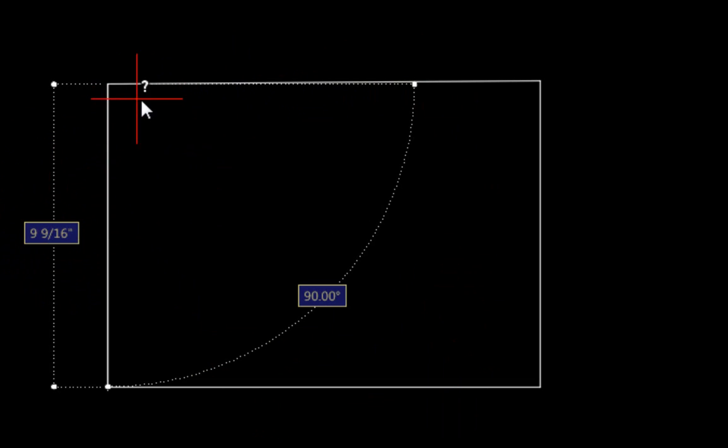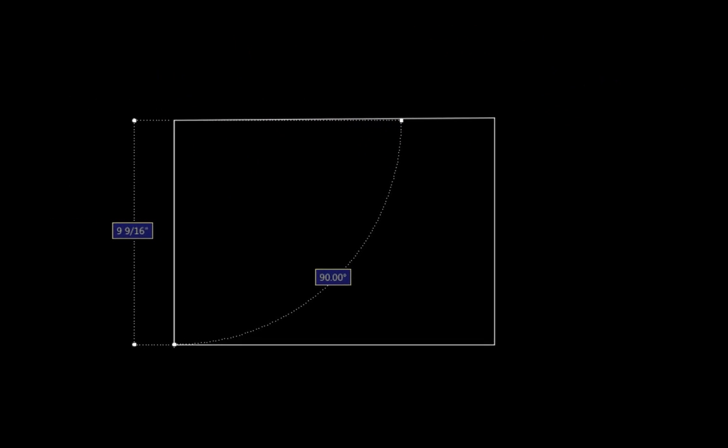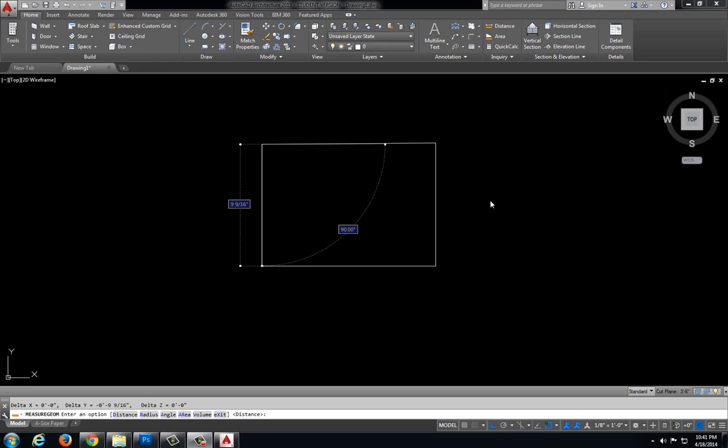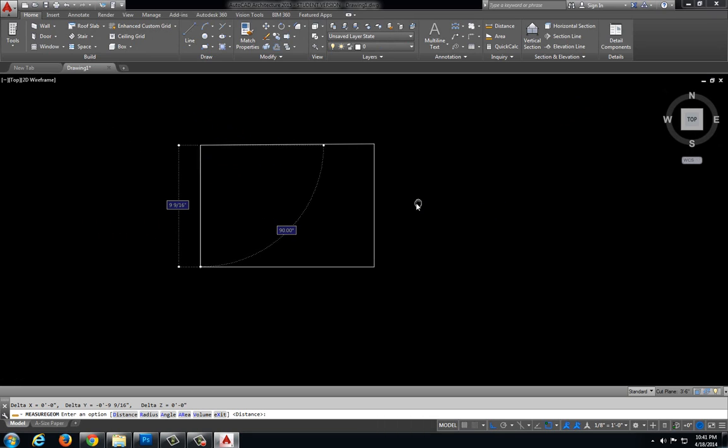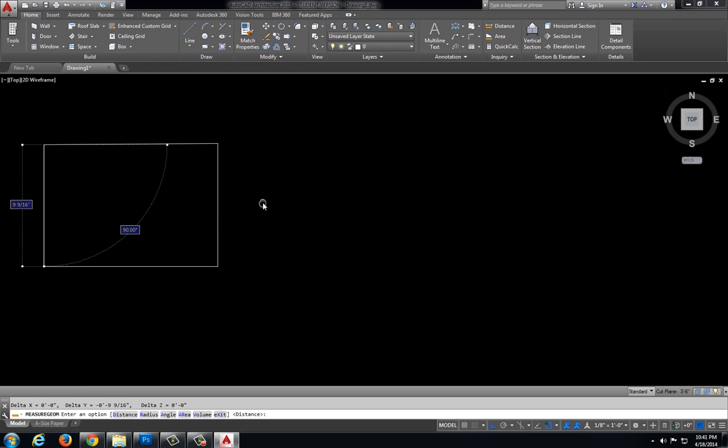These corners are not perfectly 90 degrees up at the top. We know they're 90 degrees down here at the bottom because we had ortho turned on, but up here at the top, this is actually a diagonal line that we just drew. I'm going to use my mouse, and I'm going to push and hold in the wheel, which allows me to pan the drawing, and I'm going to move that crooked rectangle over to the left.